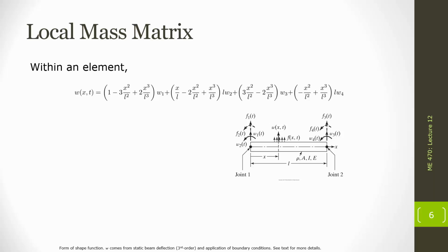And as we'll see, by using a different shape function that maybe is better if you have plastic deformation in your material or in your system, or if you have a nonlinear material, a different shape function might be more appropriate. But we're going to go with this shape function that's generally good if you have materials staying in the linear elastic region of deflection.